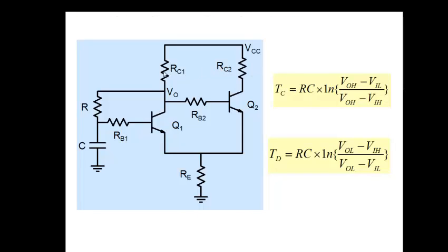So our complete oscillator then becomes that you take this point here and attach your RC to the input of the Schmitt trigger. So that's the complete oscillator. We already have expressions for TC and TD. Okay. So that's the simplified description of the oscillator.